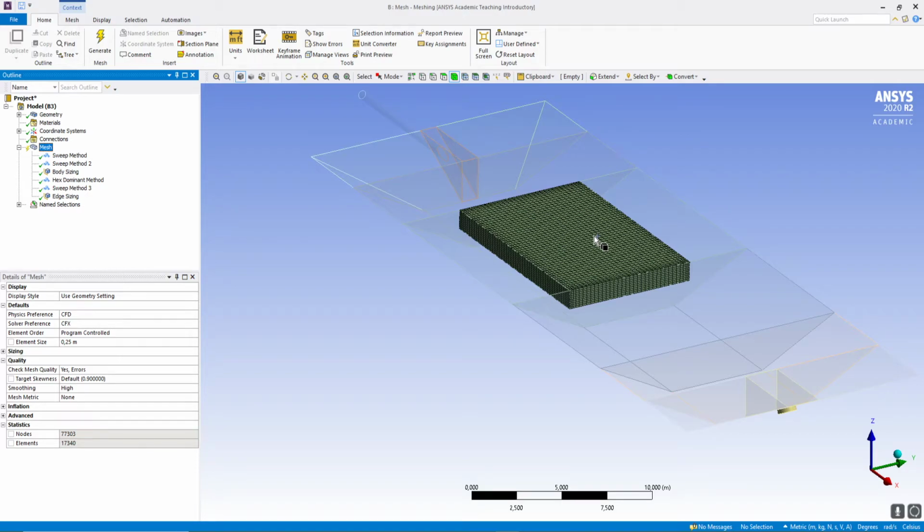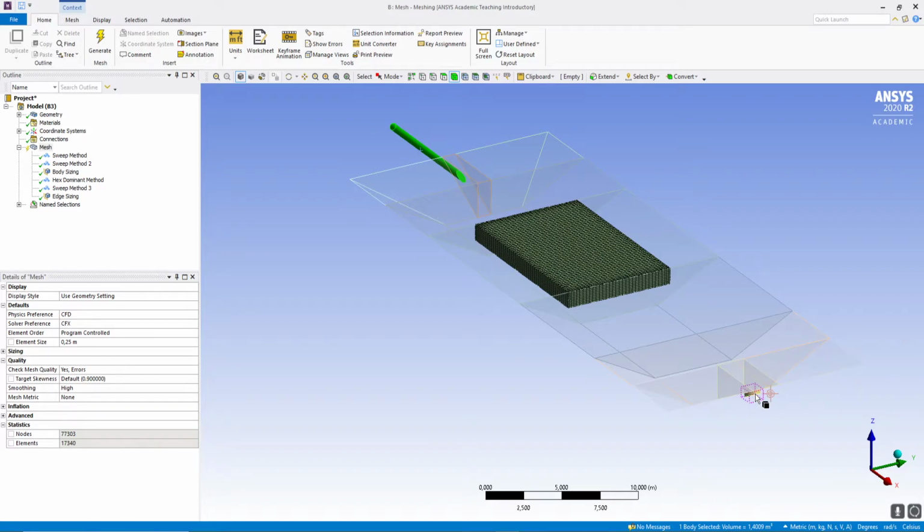remember that these functions that you use will be dictated by the critical regions of your problem. Okay, so the critical regions for our problem here are the inlet and the outlet pipe, because they are regions that will have a very high velocity gradient, and also the vegetation, because if we're studying vegetation, which is what our example will study here, this region needs to be very well defined.